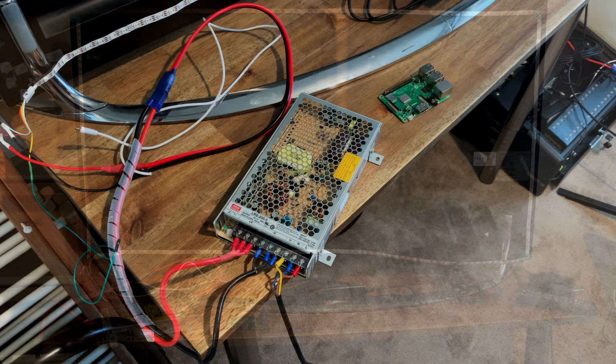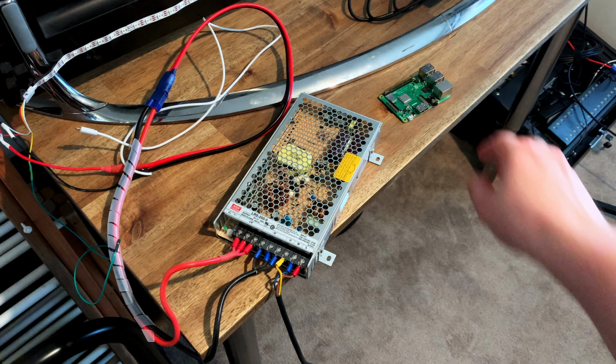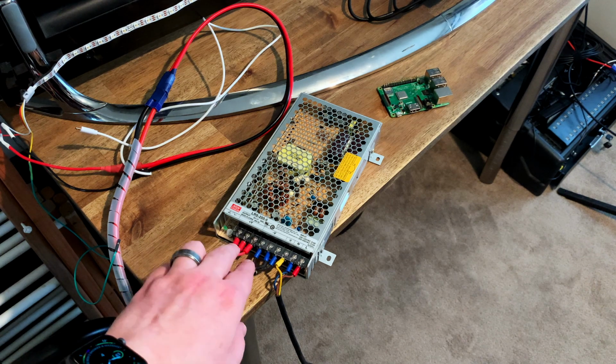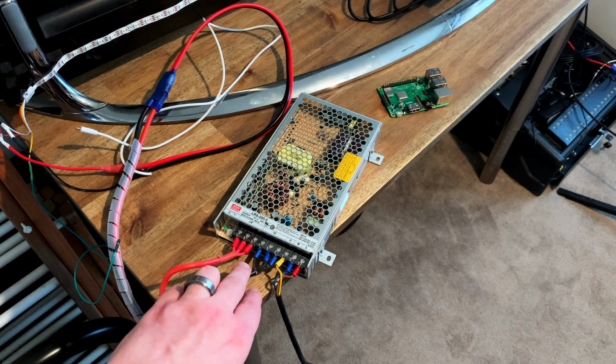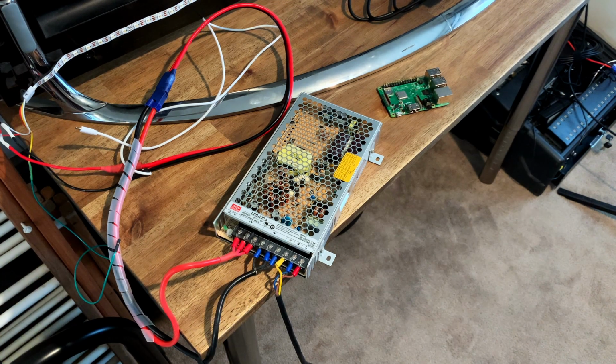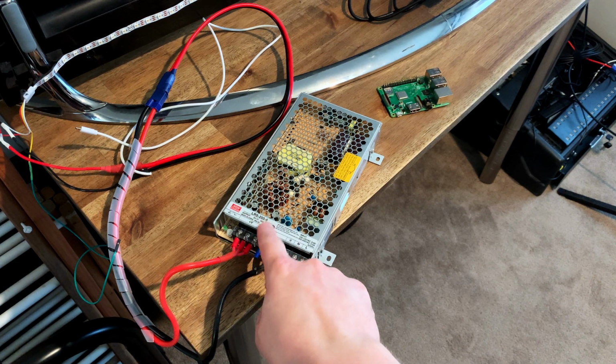Now, the hardest part about this setup is power delivery, but there is a little bit of good news here, because these particular strips, the SK6812 and the Raspberry Pi, both run off 5 volts. So we can supply power from the same source, and in fact we probably should be doing so, because provided we've got the same ground on the Pi and the strips, we won't get a lot of noise in the system. Now in my case, I'm using this Meanwell LRS 200-5 power supply.